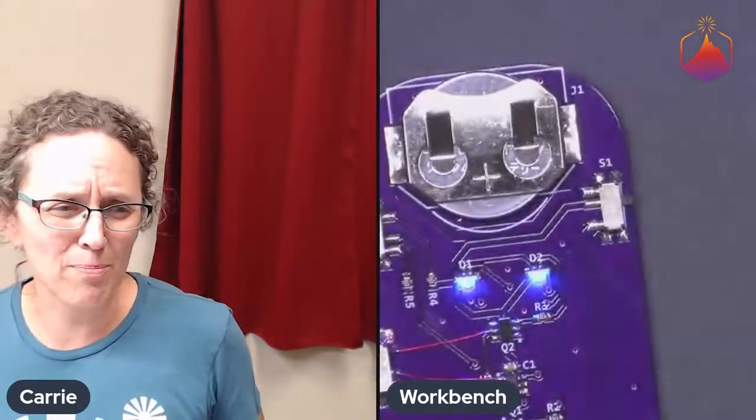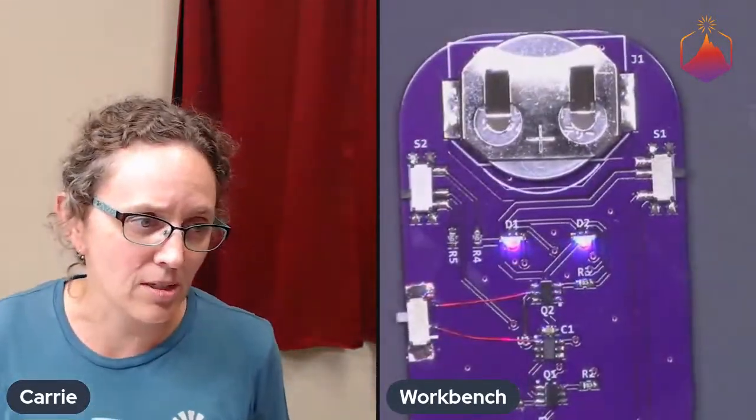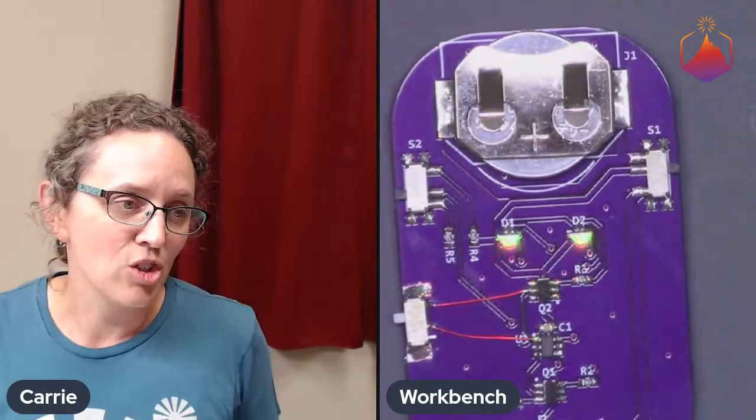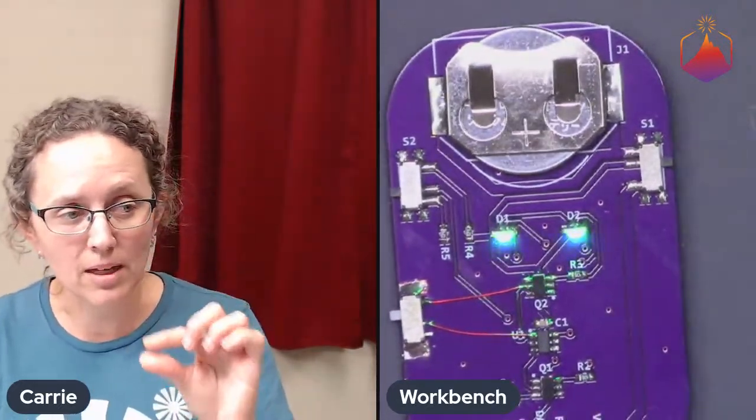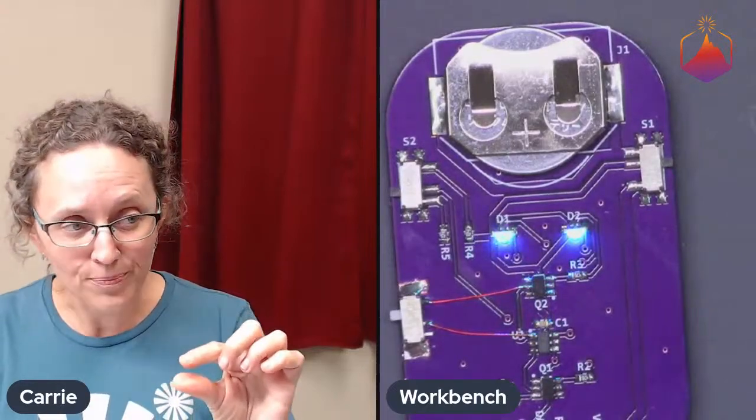There's not an LED component on the top of the board, right? You don't see anything there. Well, what's happening is the LEDs are on the back of the board, and they're actually side-mounted LEDs. And you're seeing the color through the board. I'm basically using that middle layer of fiberglass as a diffuser.